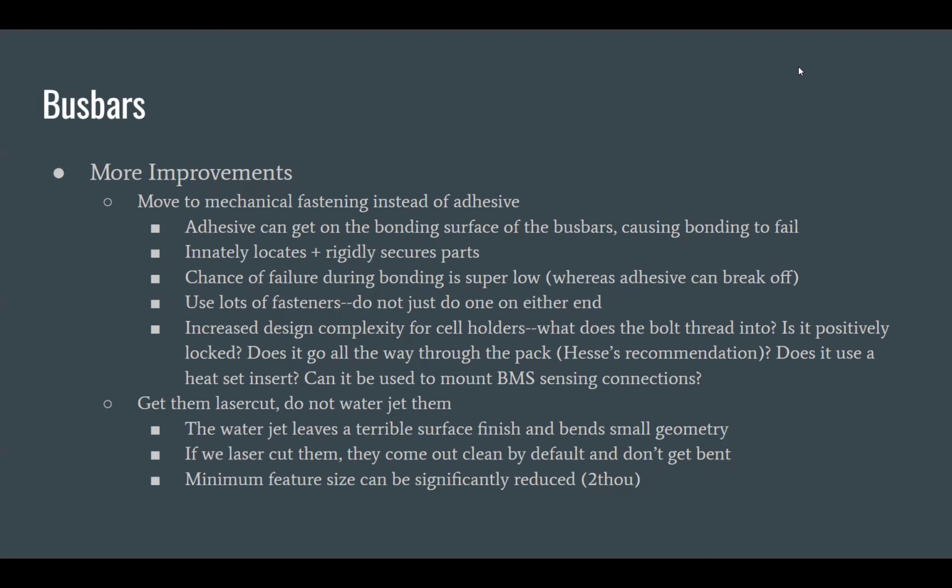Going back a little bit, why do we have segments? Why don't we just have one? By the rules, we are required to have segments, and those segments have to meet two criteria. Number one, the segments cannot exceed 6 megajoules. 6 megajoules in watt hours is about 1.66 kilowatt hours. Sorry, kilowatt hours, you're right. Yeah, about 1.66 kilowatt hours.